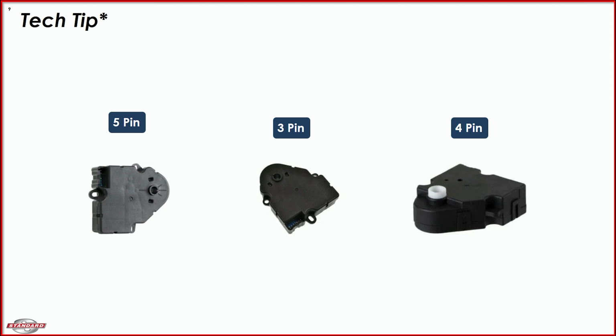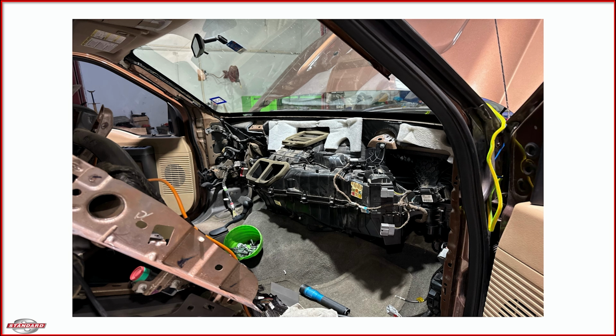Pull up the wiring schematics from the manufacturer and confirm that you're getting the right actuator for the job. There's nothing worse than ordering an actuator in anticipation of removing the vehicle dash, and after receiving the actuator and removing the dash, finding out that the actuator was not what you needed. We all know how labor-intensive it can be to potentially pull just a single actuator.